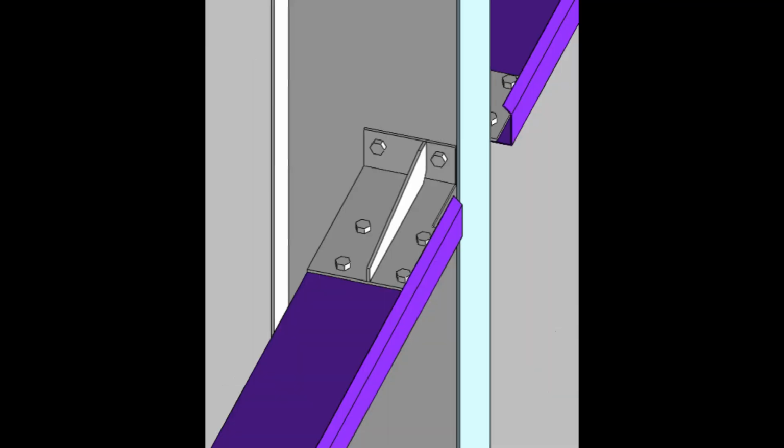This close-up view shows a secondary steel member connected to a supporting main structural member. The secondary member is attached through a bolted connection arrangement using a connection plate. A triangular stiffening plate is also visible in the connection zone. The connection transfers forces from the secondary framing member to the supporting primary structure. This type of three-dimensional close-up is useful for understanding the actual position of connection plates, bolts, and supporting members within the complete structural model.